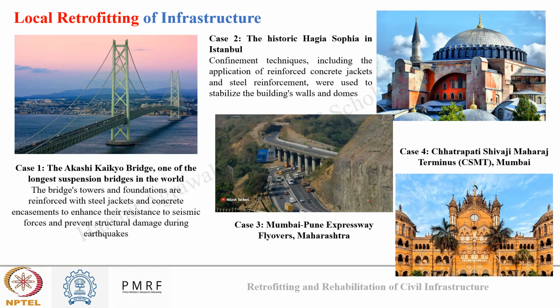Okay. Now, some cases where these local retrofitting methods were used in infrastructure, some very special infrastructures. A few examples include the Akashi Kaikyo Bridge, one of the longest suspension bridges in the world. In this, the bridge tower and foundation are reinforced with steel jackets and concrete encasements to enhance the resistance to seismic forces and to prevent structural damage during earthquakes. So these local retrofitting measures were opted in this structure to increase its seismic performance.